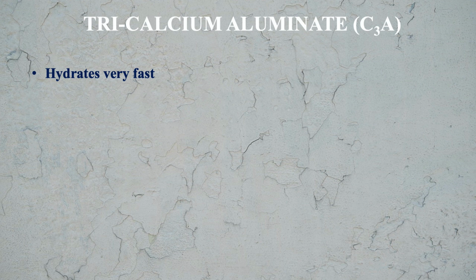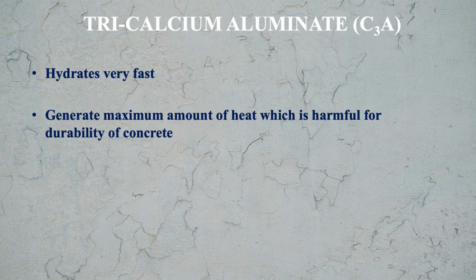Let us see first the hydration of tricalcium aluminate, C3A. The hydration process of this compound is very fast, means it hydrates very fast. It generates the maximum amount of heat, which is harmful for durability of concrete.